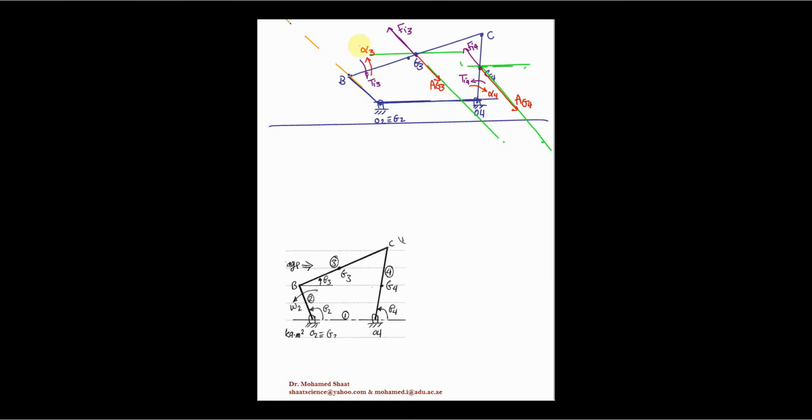This line is gonna be, let me use this color. So from point G3, I'm just gonna draw a very light line this way that is normal to the force Fi3, passing over the point G3, which is the point of intersection of the force to the link.